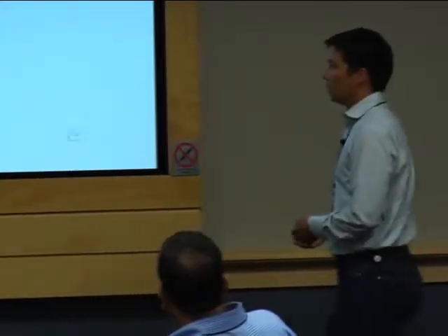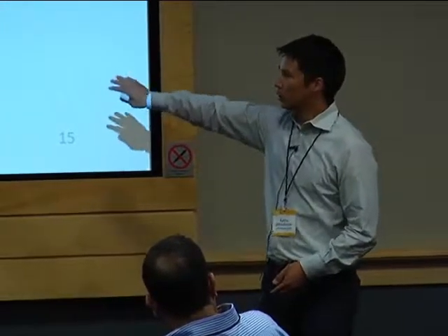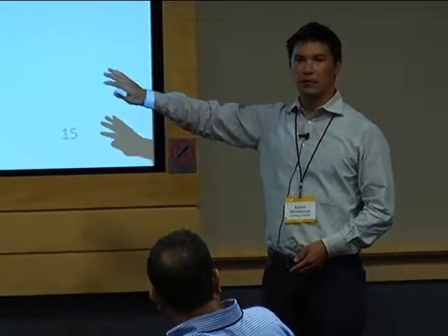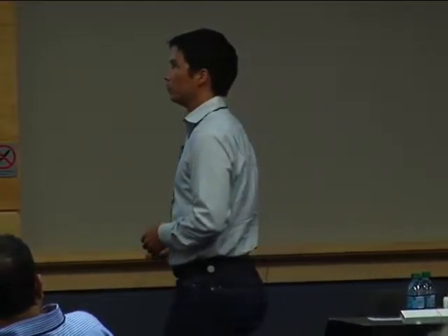It turns out that we had more maintenance calls per plugged sensor than per battery-powered sensor. The reason is that if you've got a sensing subsystem and one sensor in that system runs out of batteries, you can be pretty sure that the rest are about to run out, and so you change all the batteries for all these sensors. But the plugged-in sensors fail independently. They're unplugged in different places for different reasons. Every time one is unplugged, you need to go back and service only that one sensor. There's no way to prevent the other sensors from becoming unplugged later on. So homes weren't the power panacea that we thought they'd be.